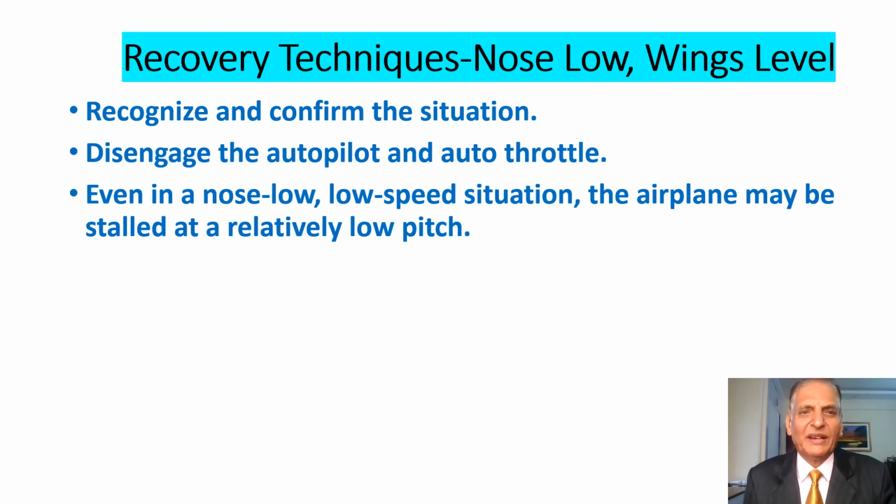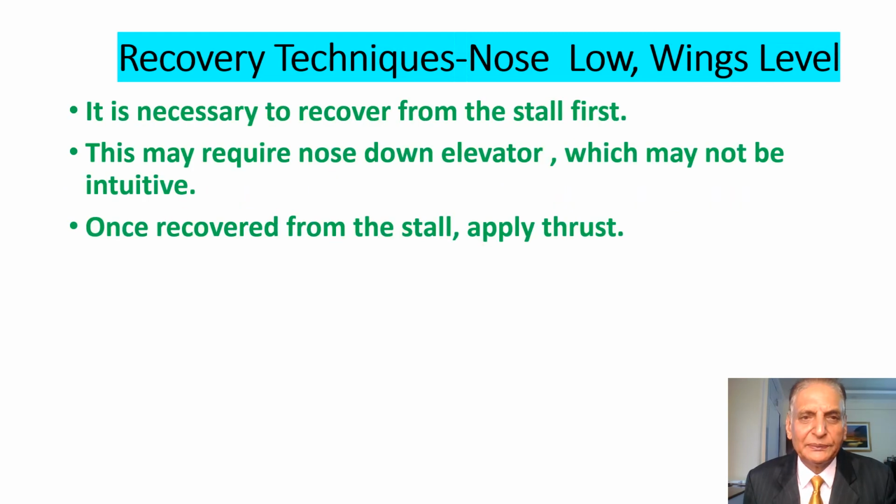Pilots must recognize and confirm the situation. They should disengage the autopilot and auto throttle. Even in a nose low, low speed situation, the airplane may be stalled at a relatively low pitch. Hence, it is necessary to recover from the stall first. This may require nose down elevator, which may not be intuitive.